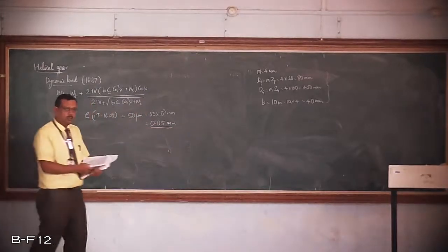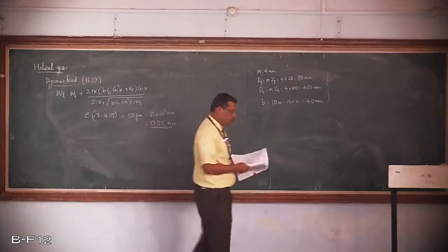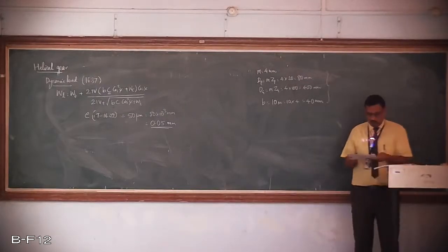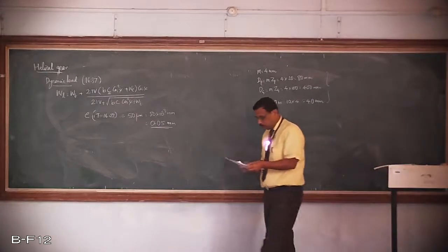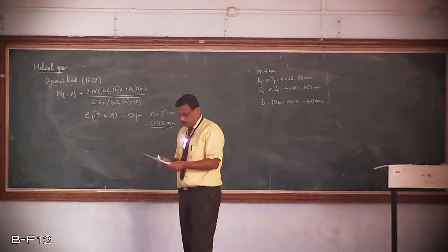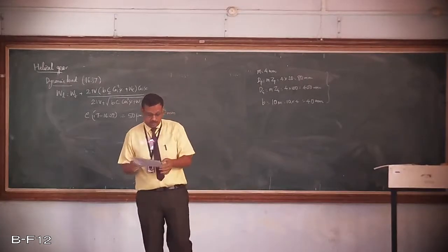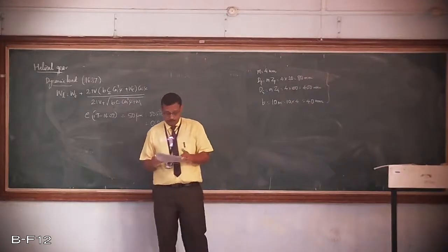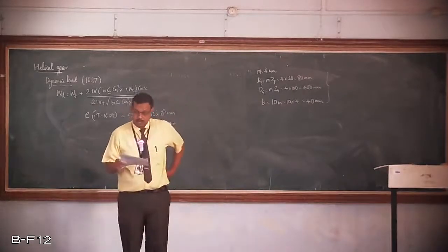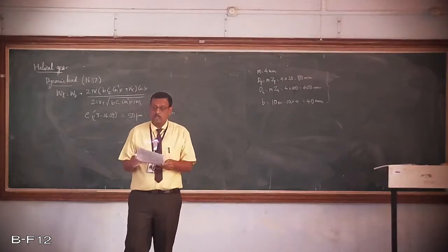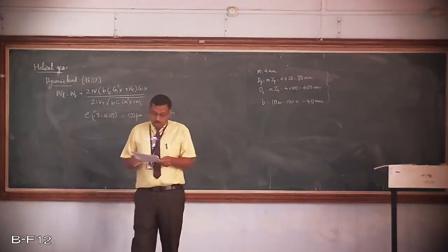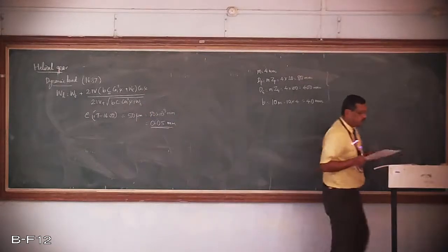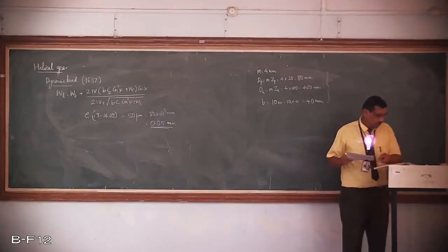So, once you know the value of error E, you can calculate the value of C using two equations. One is you can make use of the equation just below, in the spur gear, equation 16.14. You can refer to that equation: C equal to AE divided by 1 plus EG plus 1 plus 1 by EP. It is given on page number 219. Or from the table you can find out the value of C. The table is 16.5. Now let us make use of the table.